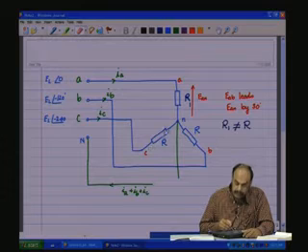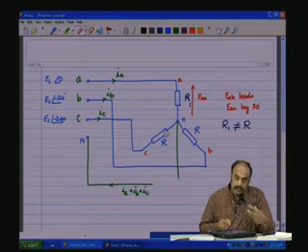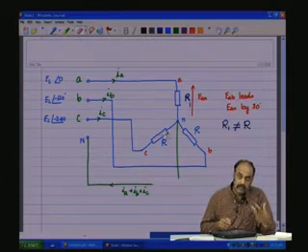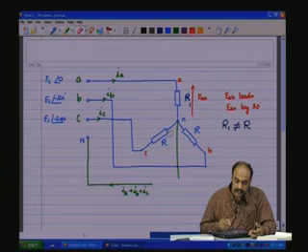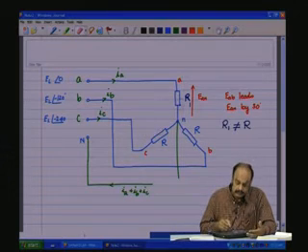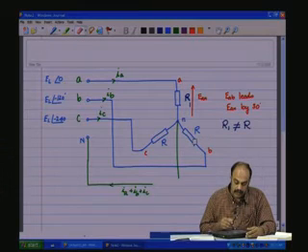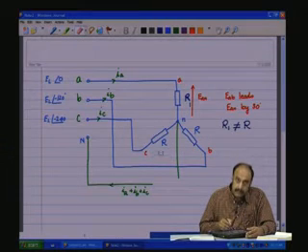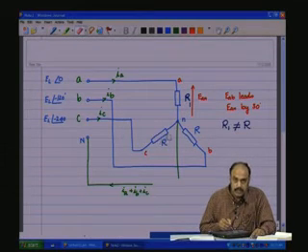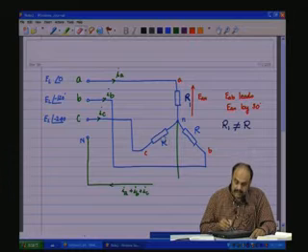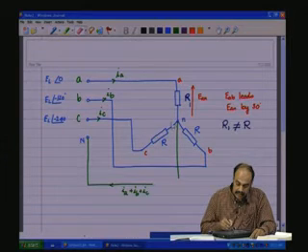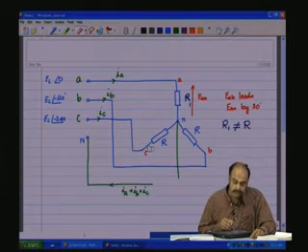So, it is not purely IC which was in the case of the balanced load that would be flowing here, and IB. So, there will be a part of IA which will get mixed into IC, and a part of IA gets mixed into IB, and those changed magnitudes of IB and IC are going to get multiplied by R and get reflected as the voltage drops.